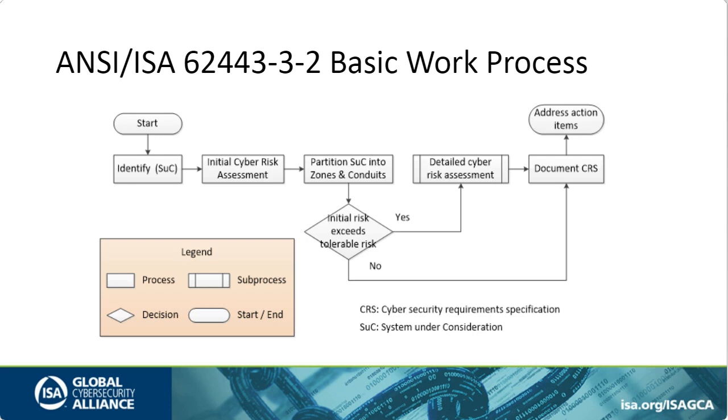Once the risk assessments are complete, they are expected to yield what's known as the cybersecurity requirements specification, and that is intended to provide the foundation, the basis for going and doing your detailed design work. Assuming that recommendations have come out of those risk assessments, they would get turned into action items, and all of the action items need to be addressed.